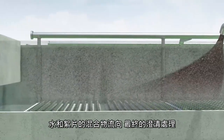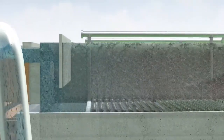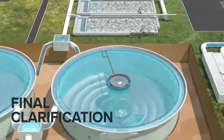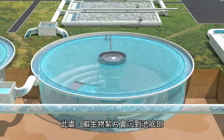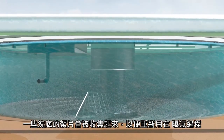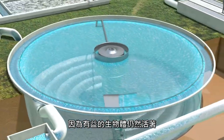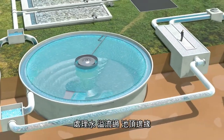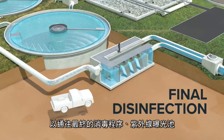The water and floc mixture travels to final clarification. Here, the floc sinks to the bottom of the tank. Some of this settled floc is collected for reuse in the aeration process, as the helpful organisms are still active. Processed water flows over the edge of the tank, en route to final disinfection in a UV light exposure tank.